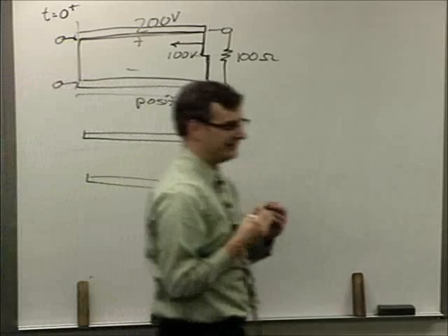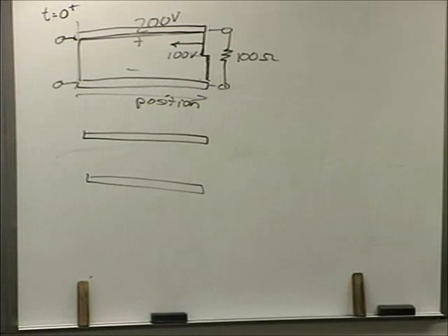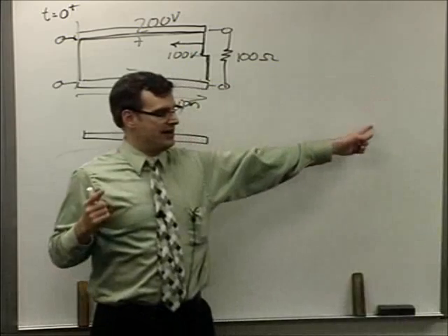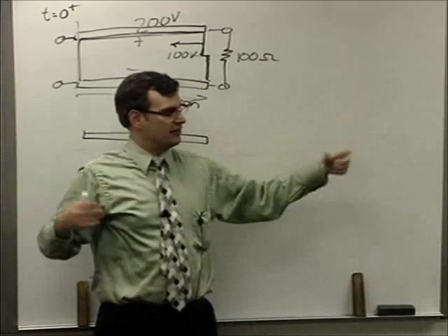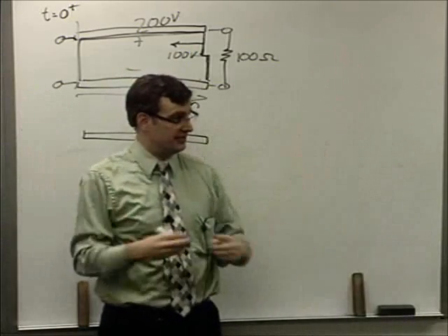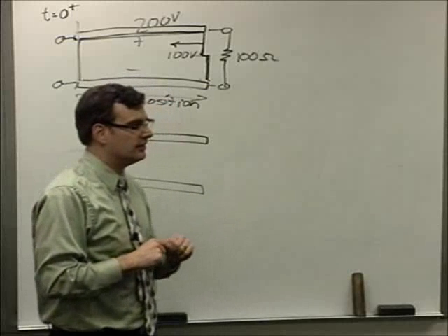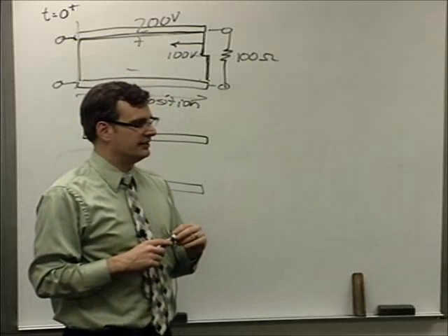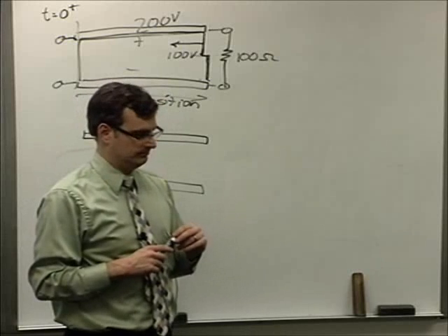Yes, you have a question? I was a bit confused because earlier I guess we had both ends open. That's right. Reflection coefficient of 1 at both ends. And you said that 100 was coming across the top and then 100 was going on the bottom, like a loop cycle. Yeah, 100 volts going this way, 100 volts going that way, both feeding one another because the reflection coefficients were +1.